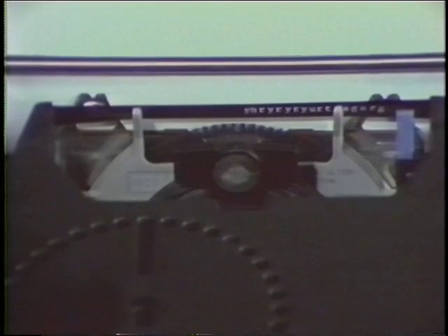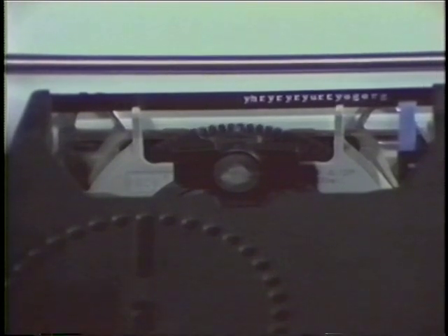The ribbon lift motor drives the ribbon plate to its highest lift position and back to home. This homes the ribbon lift motor and checks for an overcurrent condition of the lift motor. The machine also checks the ribbon feed motor by driving it long enough to feed the ribbon approximately 1 character. The ribbon feed motor is also being checked for an overcurrent condition.